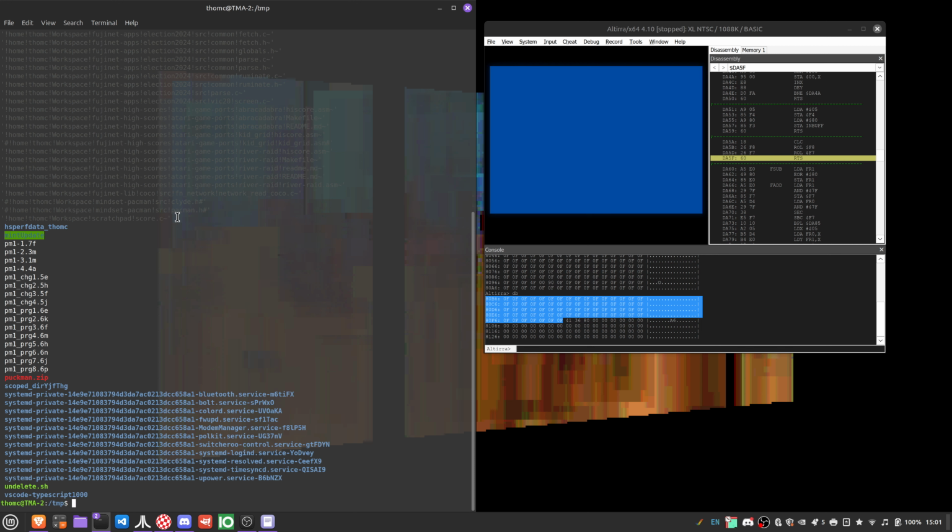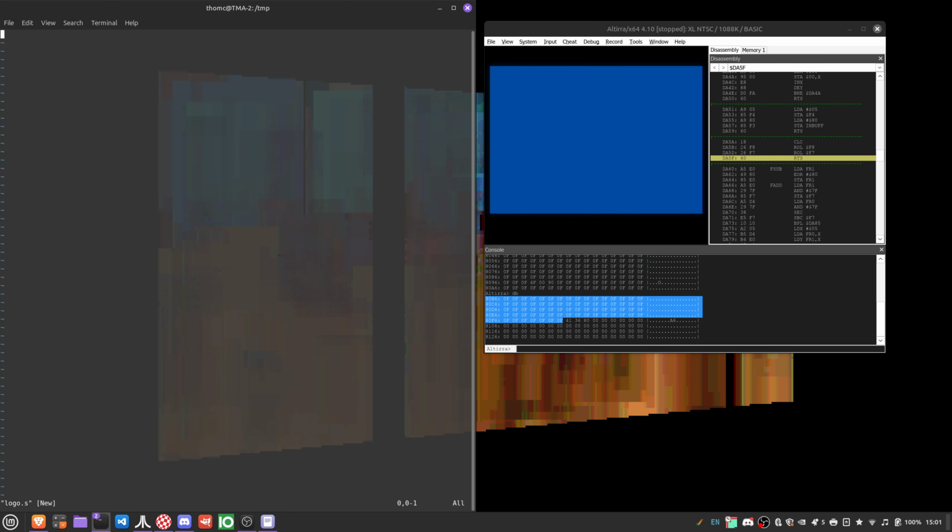So I'll start with the first bits of this. You can use whatever assembler you wish. It really doesn't matter. You have full choice here. I'm going to use the MAD assembler. We need a handful of equates to help us along. To start off with, we need an equate for VDLST. This is the vector for the display list interrupt. It lives at 0200, and we also need the shadow location for where ANTIC needs to point its display list pointer. That lives at address 230.